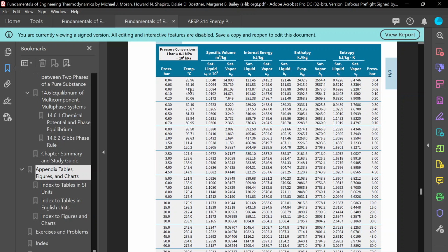and you are going to remain at the saturation condition. So for point 2, you already have the entropy of the liquid part of your system and the entropy of the gas part of your system. You can read it from the table. You have it right here. The only thing you don't have is the vapor quality. How much of your system is gas? How much phase change has that expansion in the turbine caused?